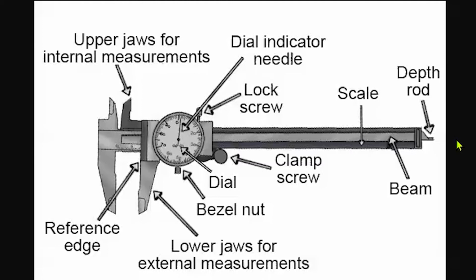The internal, external, and depth measurements will be the same at any given distance. Dial calipers are normally accurate to within their scales. However, because of their nature and operator use, I wouldn't use them for tolerances of 5 thousandths or less.